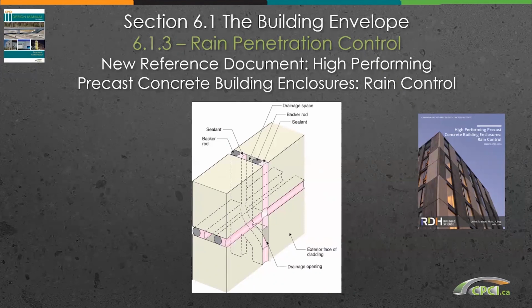This requires the installation of tooled sealant on a backer rod installed about 75 millimeters or 3 inches behind the outer face. Weep holes with a minimum dimension of 12 millimeters or 1/2 inch to facilitate drainage are almost always provided in the vertical joints. A bead of sealant is tied to the interior vertical sealant bead with an outward slope and a drop in height from the horizontal joint of at least 100 millimeters or 4 inches, thereby encouraging outward flow of water and resisting the entry of wind-driven rain.